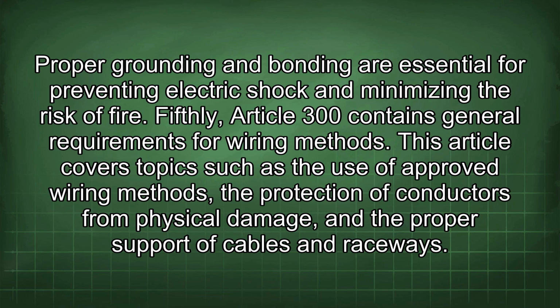Fifthly, Article 300 contains general requirements for wiring methods. This article covers topics such as the use of approved wiring methods, the protection of conductors from physical damage, and the proper support of cables and raceways.